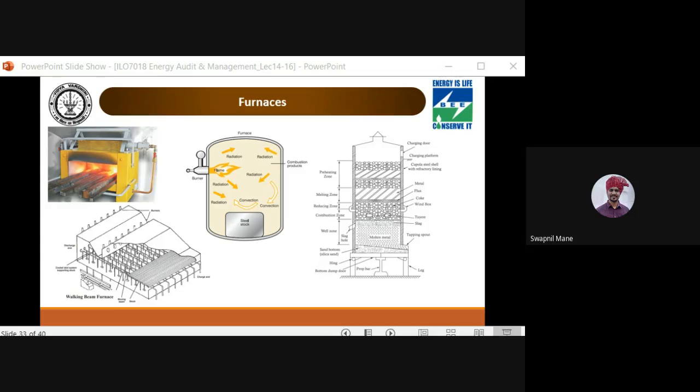As combustion takes place, the charged material, that is the coke, flux and metal, descends downwards, while the hot gases due to combustion ascend upwards. Heat exchange takes place between the rising hot gases and the descending charge, thereby melting the metal. So the liquid metal drops down while the coke floats on top of it.